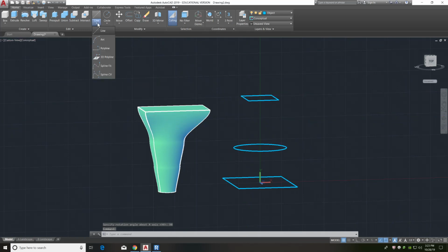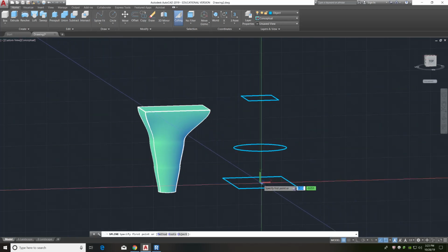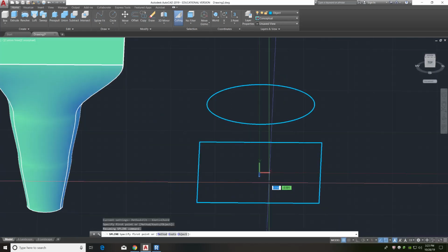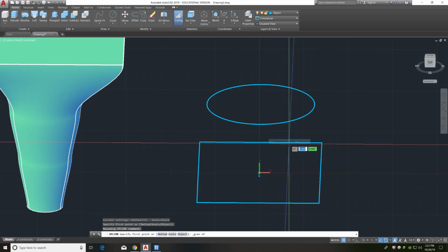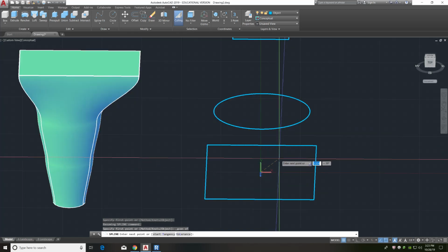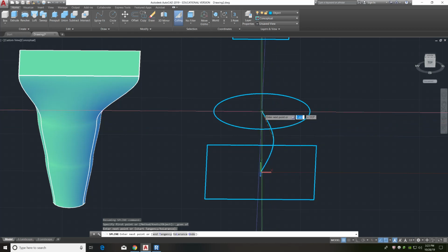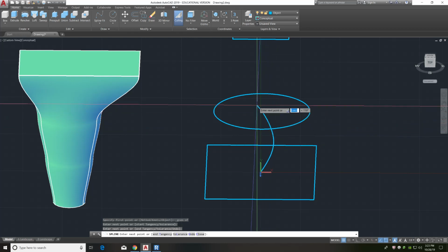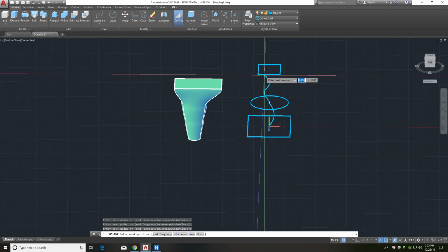And basically what I'm going to do is open up the line tool and go to the spline command. That's probably the easiest. And from the spline command, I'm going to shift right click, see if I can get the geometric center. There it is. And I'm going to be clicking from one cross section, I just hit the center over there, to another cross section.